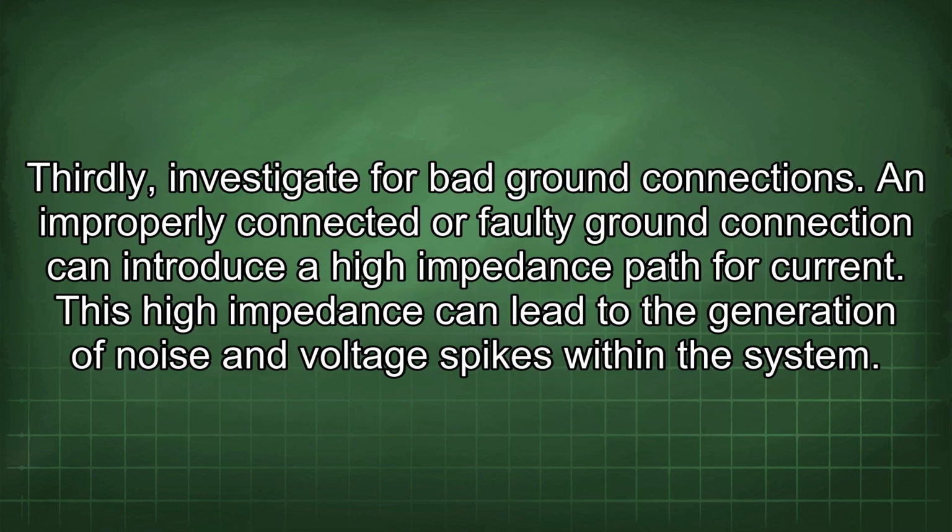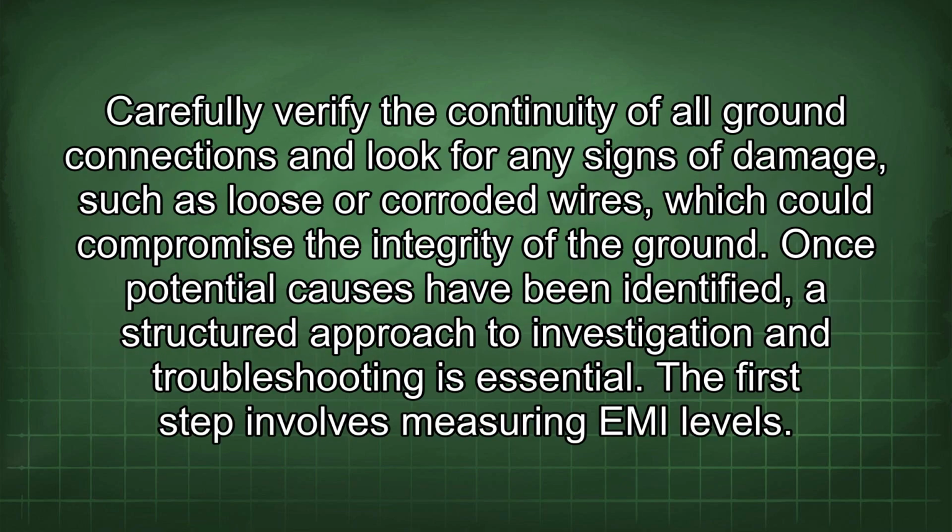Thirdly, investigate for bad ground connections. An improperly connected or faulty ground connection can introduce a high impedance path for current. This high impedance can lead to the generation of noise and voltage spikes within the system. Carefully verify the continuity of all ground connections and look for any signs of damage such as loose or corroded wires, which could compromise the integrity of the ground.